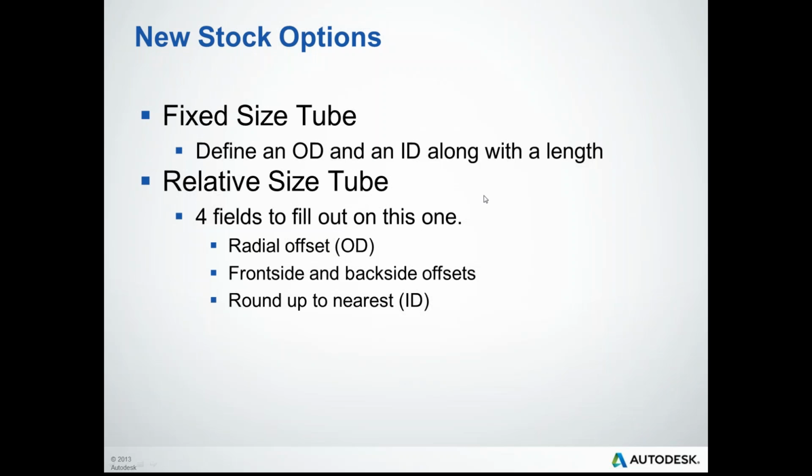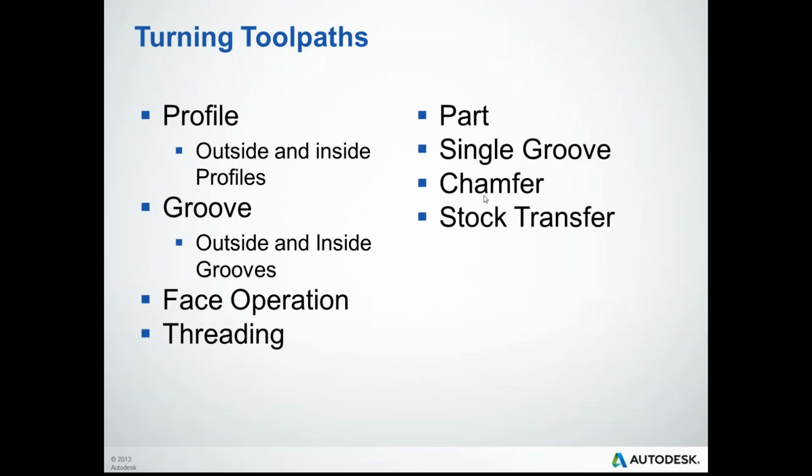And then with turning, all the toolpaths that are involved with our turning option are profile, where within profile you can define whether you're doing outside profiling or inside boring, grooving, outside or inside facing operations, threading, parting, single grooves, chamfer option, and stock transfer for multiple spindles.